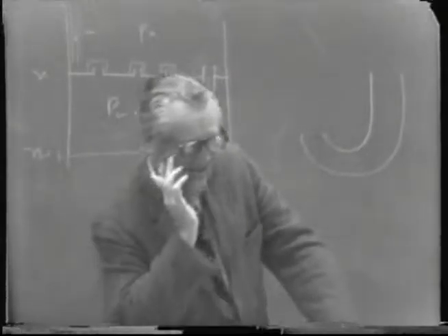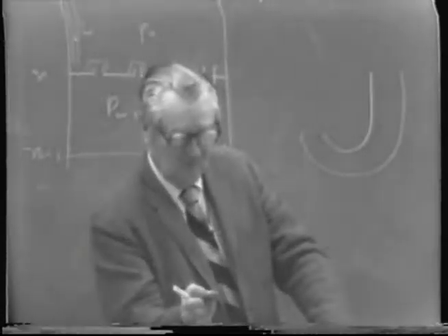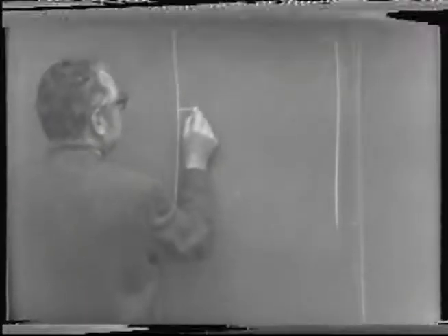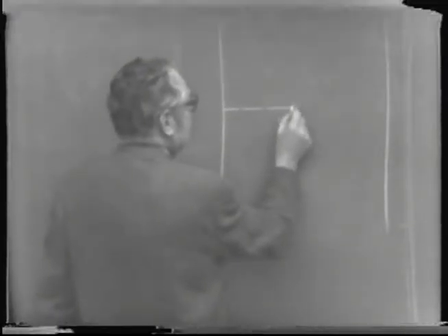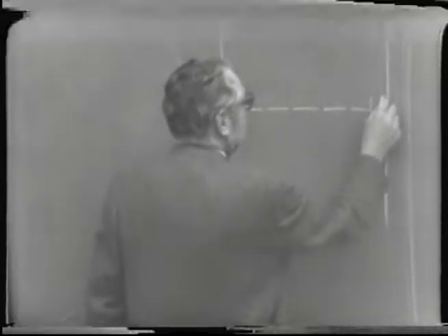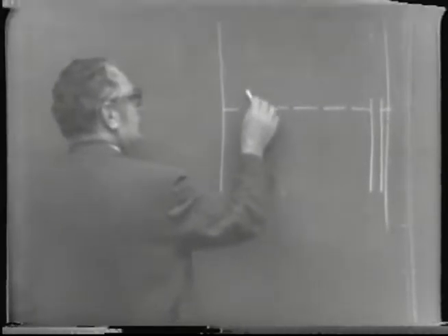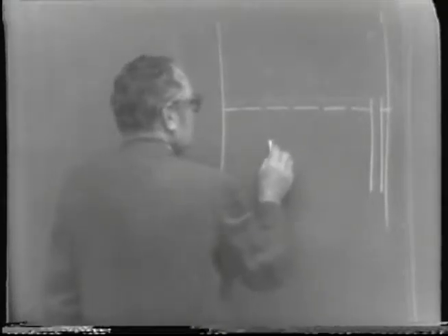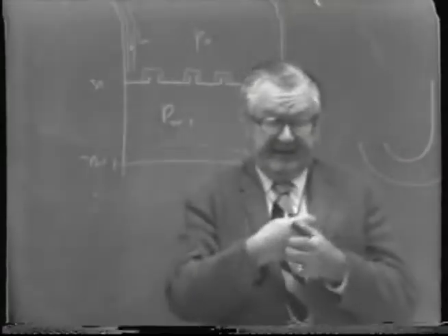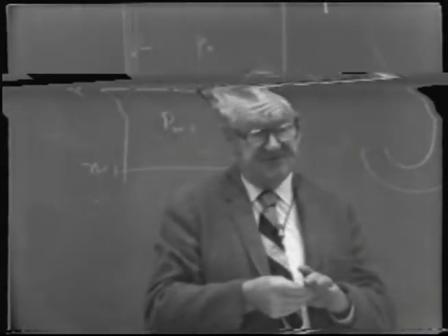Oh, well, I haven't really dwelt much on this question of hole diameters, but the whole concept or principle of the functioning of a sieve plate is to balance the tendency for the liquid to run through the holes against the pressure drop occasioned by the vapor passing through the holes. And also the surface tension enters in here too.